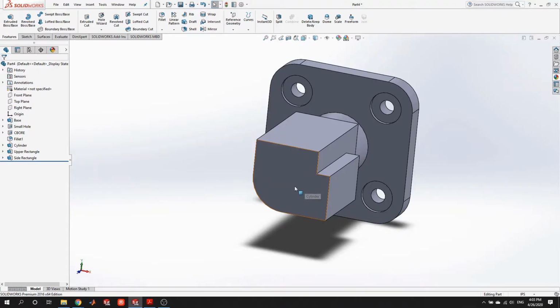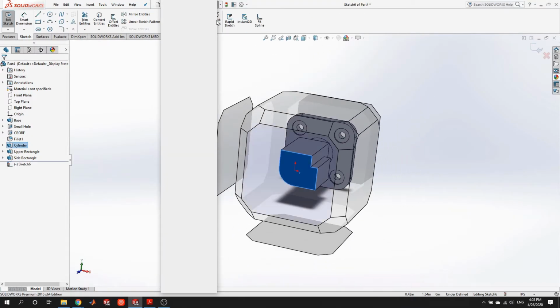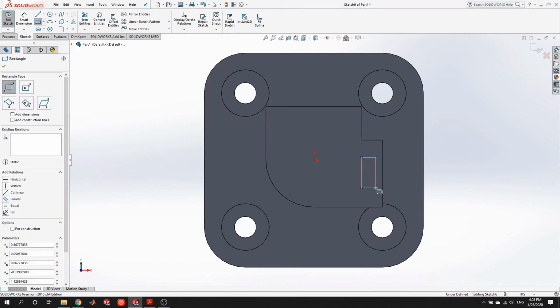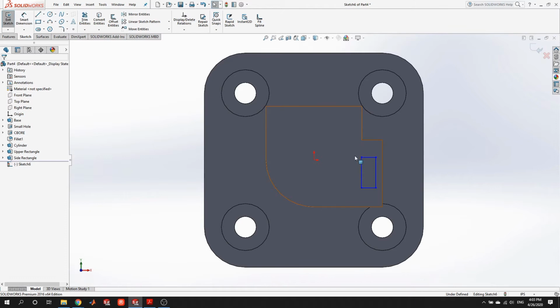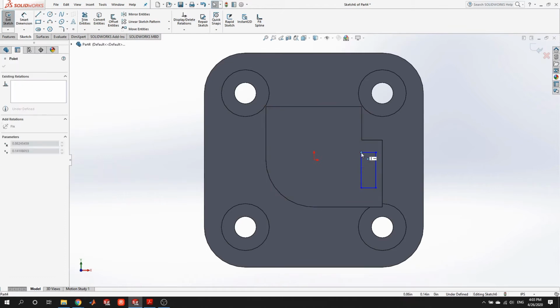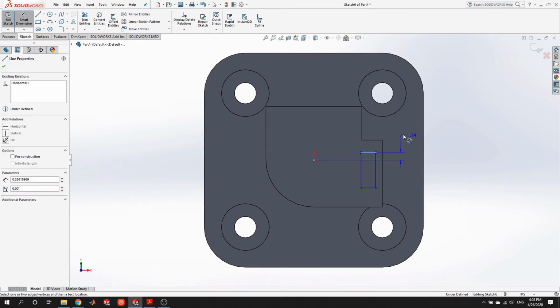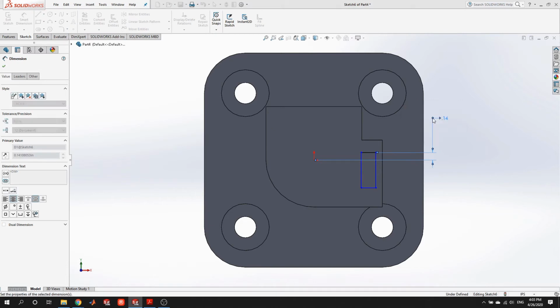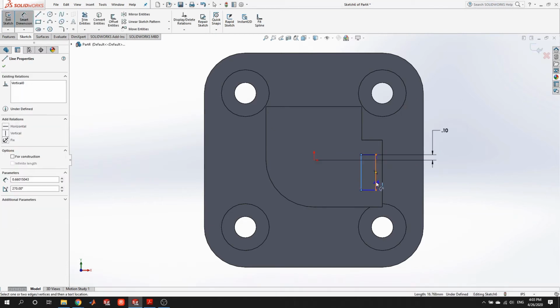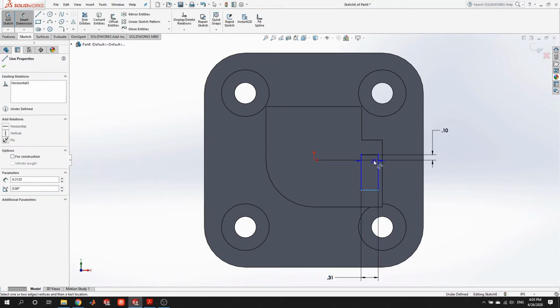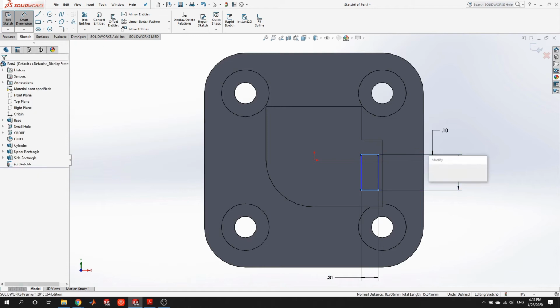So we're going to insert a sketch on the front of that cylinder again. Put in a rectangle. Okay, so now let's make sure that we drag the top of this rectangle certainly above the origin so that we can dimension it easily. So from the origin, which is the center of the circle, this is 0.1 inches. The width is 0.3125. And then the height is 0.625.